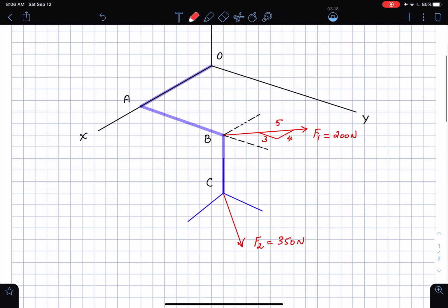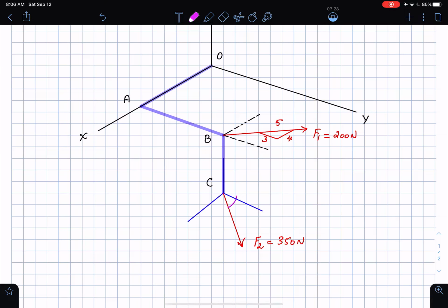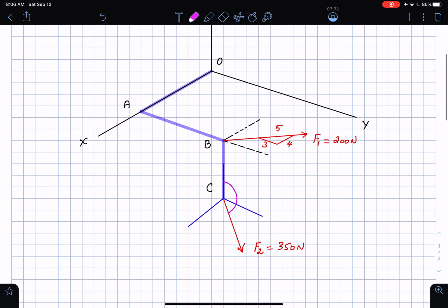And then I'm given angles for this force. Watch this. From the tail of this force, I'm going to draw these angles in maybe the magenta or the purple color. From the tail of this force all the way to this vertical line here, which is essentially parallel to the z direction, I'm given the angle to be 120 degrees, which you can recognize as the coordinate direction angle.